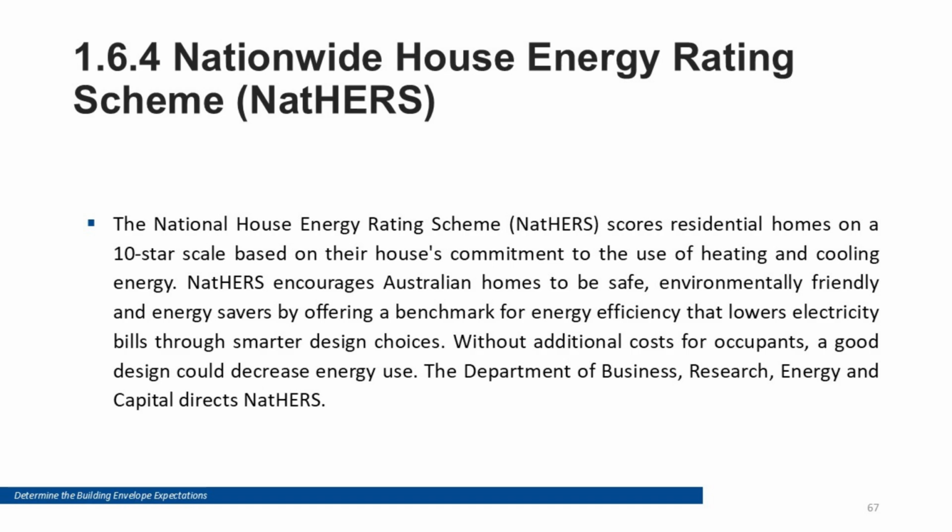Nationwide House Energy Rating Scheme (NatHERS). NatHERS ratings are sensitive to build quality. Changes like missing insulation, poor sealing, or different glazing can reduce the expected rating and increase heating and cooling demand. Good practice is to protect the intent of the rated design and confirm critical envelope details during construction, including insulation continuity, sealing around openings, and correct window and door specification.